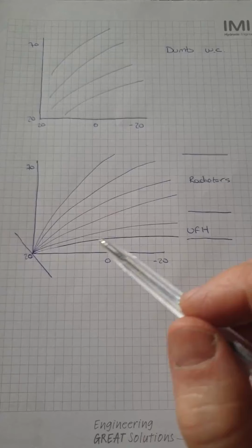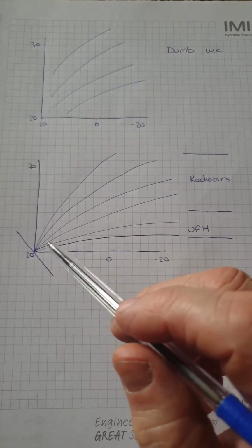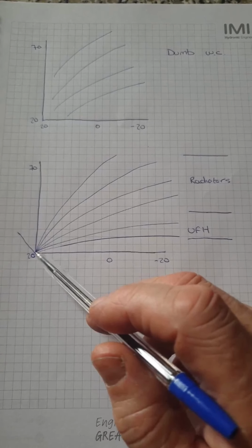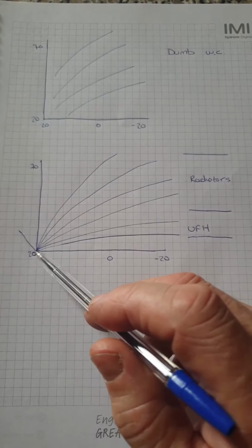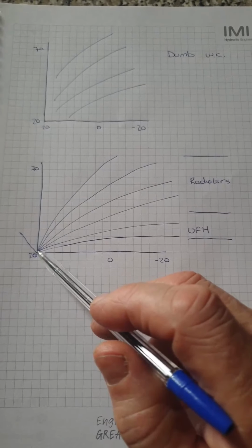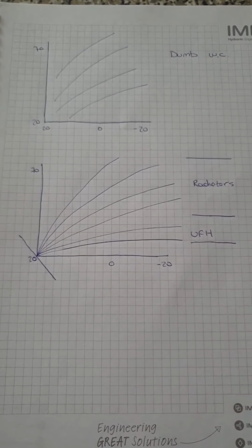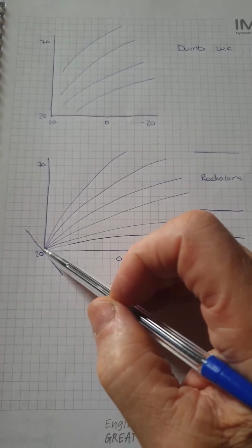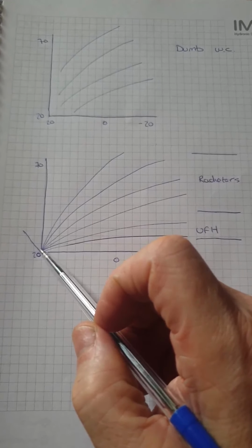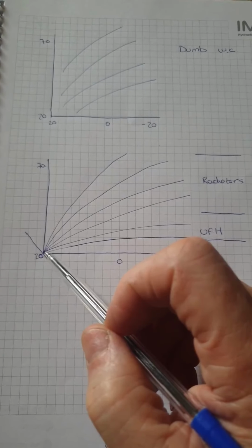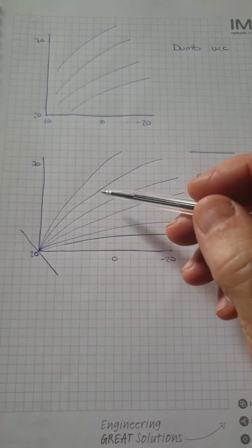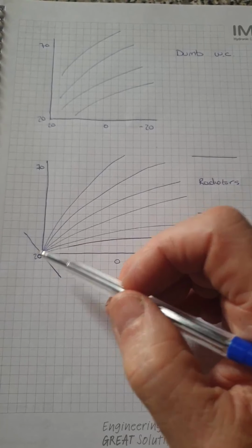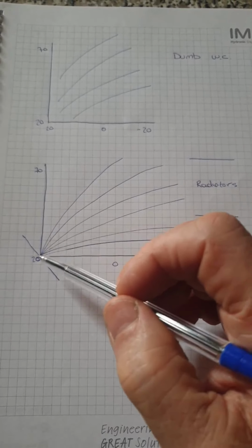So basically all the curves on the Viessmann weather comp amalgamate back at a start point, and this start point is usually a match between the flow temperature and the design room temperature. So this would be a flow temperature of 20 and a room temperature of 20, and kind of worked out that the delta T at this point would be 0, and the reason it'd be 0 is pretty much it's turned off because there's no heat requirement. And what I believe happens is that at your main design function you'll have your delta T20, but that delta T is going to drop back and narrow as we come back down this curve.